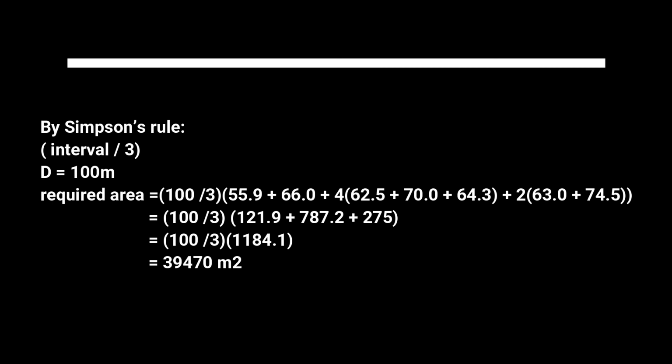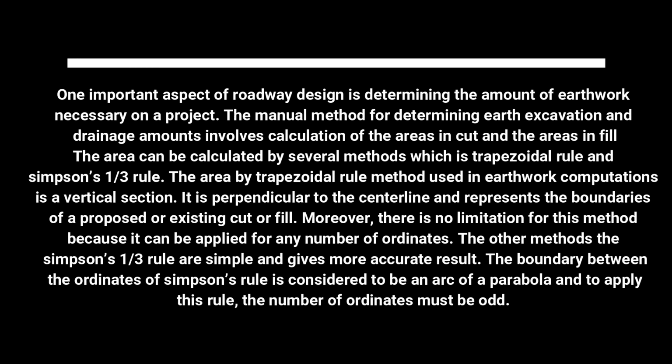39,470 meters square. For discussion, one important aspect of roadway design is determining the amount of earthwork necessary on a project. The manual method for determining the earth excavation involves calculation of the area in cut and the area in fill. The area can be calculated by several methods such as the trapezoidal rule and Simpson's 1/3 rule.